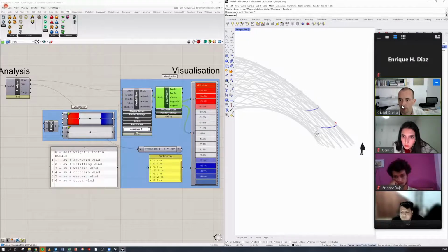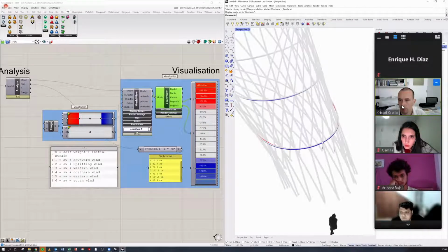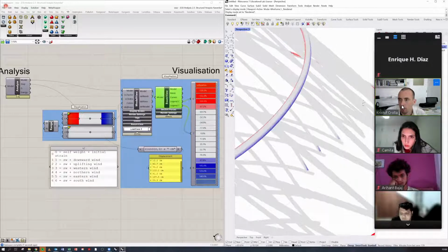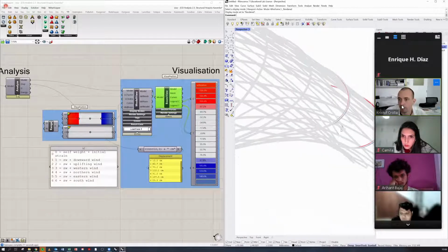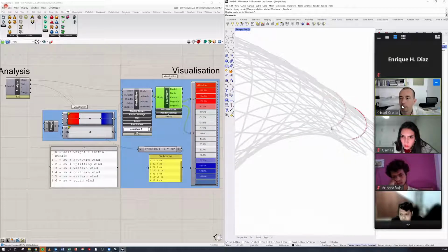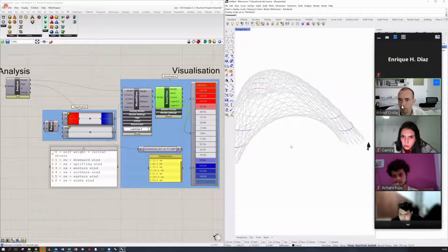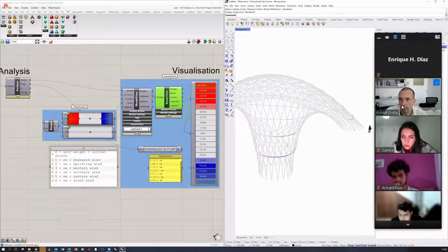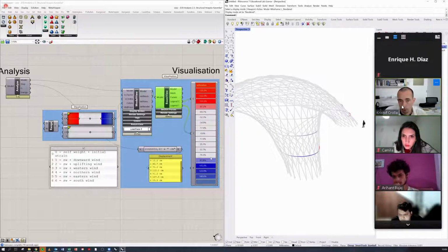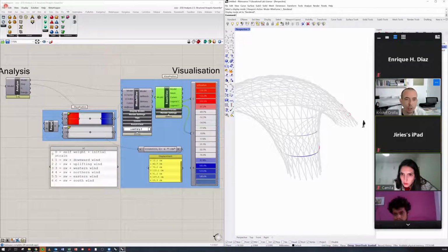It's overstressed in some of the corners, tension on the outside, compression on the inside. And then you'll see in some of the foundations a little bit of cracking happening in the model, but that's negligible. So this actually shows us that in the normal load case scenarios, it would break there, which is what happened on site. Here we had to nudge our bamboo poles and artificially bend them to make it work.